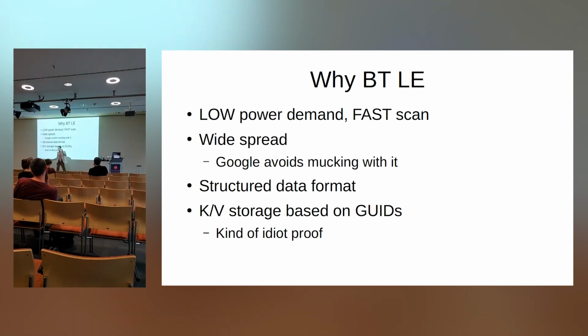The other benefit of Bluetooth LE is that when you use it, you implicitly get support for versioning. The biggest mistake in an embedded project, take it from me, is that people don't think about versioning. You need to think from the first minute on how you can evolve the protocol. And Bluetooth LE makes this very simple because you simply add an extra mailbox for the new functionality, and the old app simply interacts with the old mailbox. Who cares if there's an extra mailbox on the door of his house? Nobody. And that's much the same approach for Bluetooth LE.